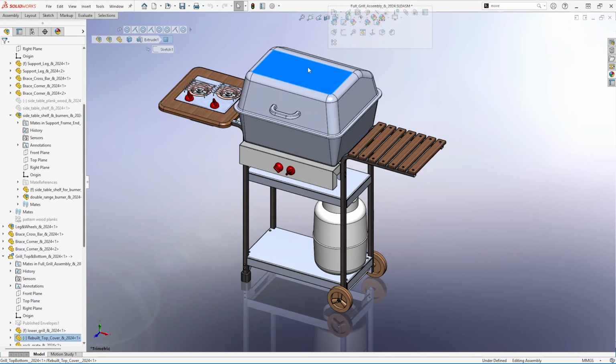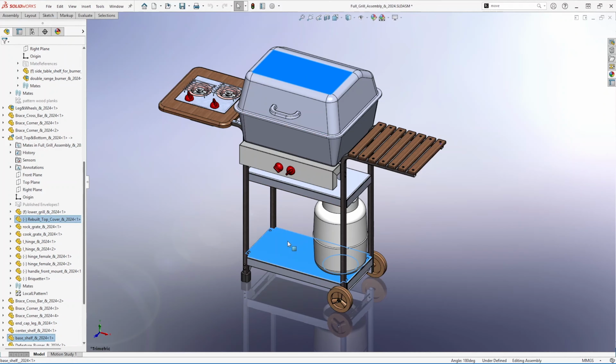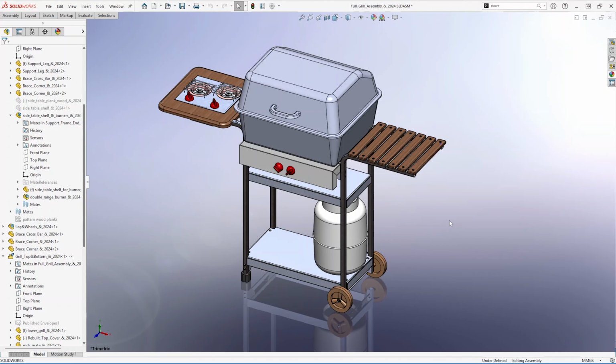We select groups of components all the time in SOLIDWORKS assemblies for many different reasons: for suppression, visibility, appearance, or as references for mass properties or interference detection. Well, we have advanced selection tools that allow us to make mass selections of components based on certain logical criteria.